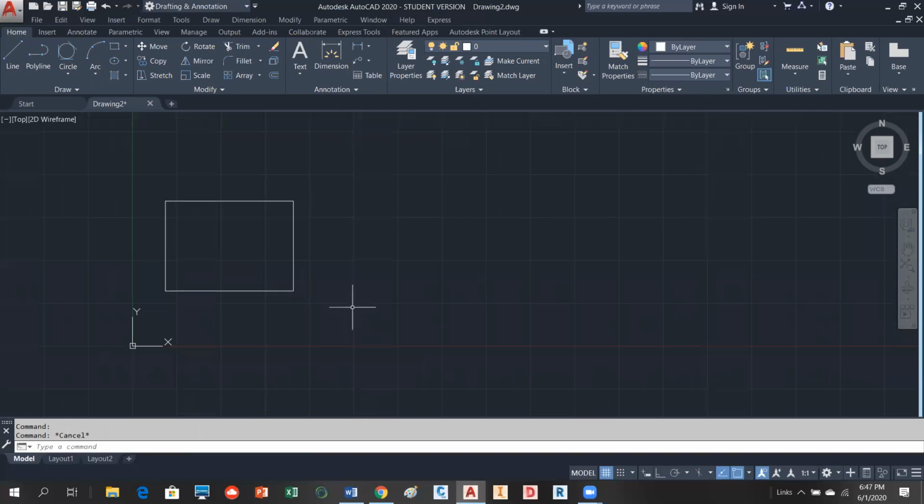Okay, so if we look at the rectangle command again, notice there are what we call width. And width will allow us to take this thing and pull it out this way and this way. So in other words, make the lines thicker, okay? And in drafting terminology, when you make a line thicker or darker, that's called giving it line weight. So what we're doing in this polyline, we're going to give it width. So we're going to choose this width option, where you can just type in W, and it wants to know the width, okay?